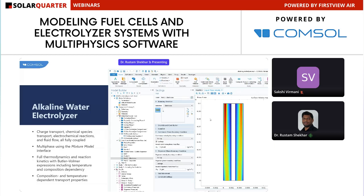So recently, people have had interest in alkaline water electrolyzers, because they're cheaper compared to the PEM fuel cells, and they are giving better performance than the PEM fuel cells. So you can design your alkaline water electrolyzers along with the two-phase flow, where we are using the multi-phase mixture model, and again full thermodynamics reactions or Volmer expressions, and the composition and temperature dependent transport properties have been given. And here we have solved the charge transport, chemical species transport, electrochemical reaction, and fluid flow in a fully coupled manner.